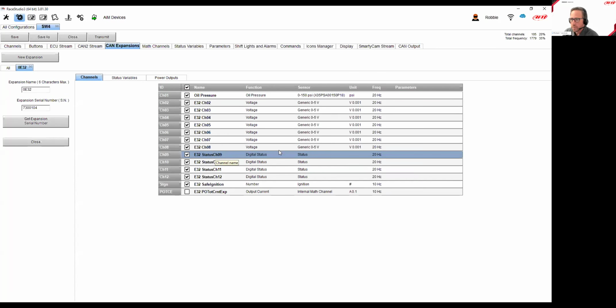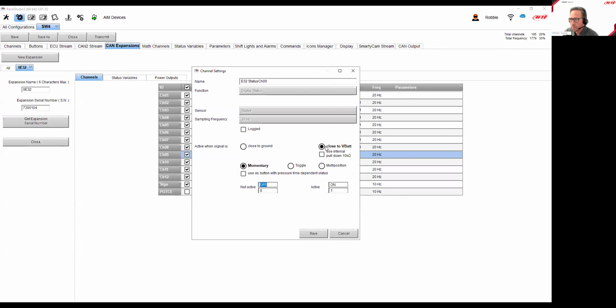Digital outputs, you'll still have the access to the internal pull up and pull down. Now these are just switching devices. If I had a binary state that's coming in, a 0 or a 1, an ignition switch, like if I put a key in and it's either on or off, or a button that I want to add externally, I would add these here. And these are really good for signals coming from an ECU that tell you when to turn on a fuel pump.